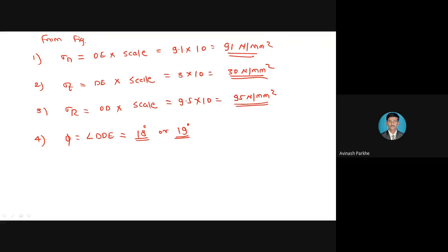Then take the inclined radius only, either CH or CG, and draw one circle. And once you have drawn the circle, again to represent the 2 theta angle, select the inclined line only. In case number 2, from point A, in the anticlockwise direction, we were representing the 2 theta angle. But in case number 3, from the inclined line or point G, we are representing 2 theta in the anticlockwise direction.